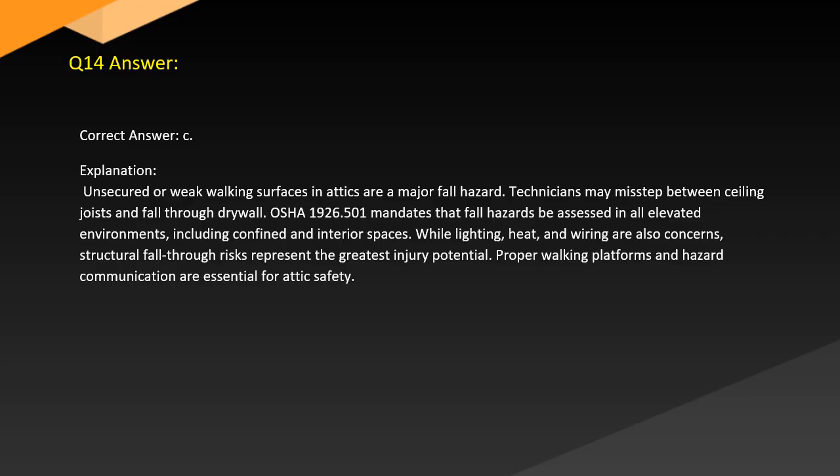1926.501 mandates that fall hazards be assessed in all elevated environments, including confined and interior spaces. While lighting, heat, and wiring are also concerns, structural fall-through risks represent the greatest injury potential. Proper walking platforms and hazard communication are essential for attic safety.